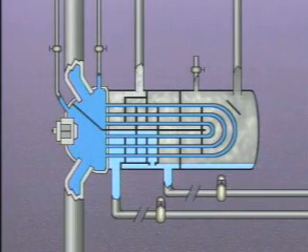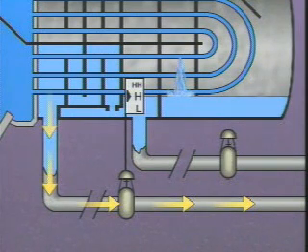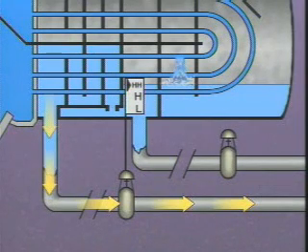Tube leaks are another common operating problem associated with closed heaters like this high-pressure feedwater heater. Even small leaks can significantly increase the volume of water in the drips, causing the lower tubes in the heater to be blanketed with feedwater. Tube leaks also make the heater's level control valve open farther than normal. As a tube leak becomes larger, the volume of water flowing into the shell side of the heater can exceed the level control valve's capacity. Then the emergency drain valve must be used to control the level in the heater.